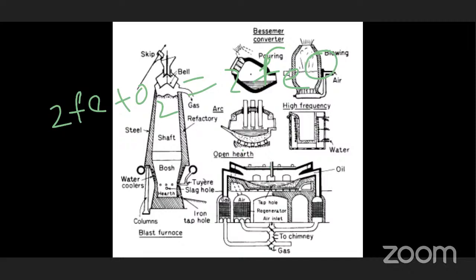So then the iron oxide reacts with the impurities. The iron oxide that is contained in the converter will react with the impurities, and thus the elements like silicon, manganese and carbon are eliminated in the order indicated.